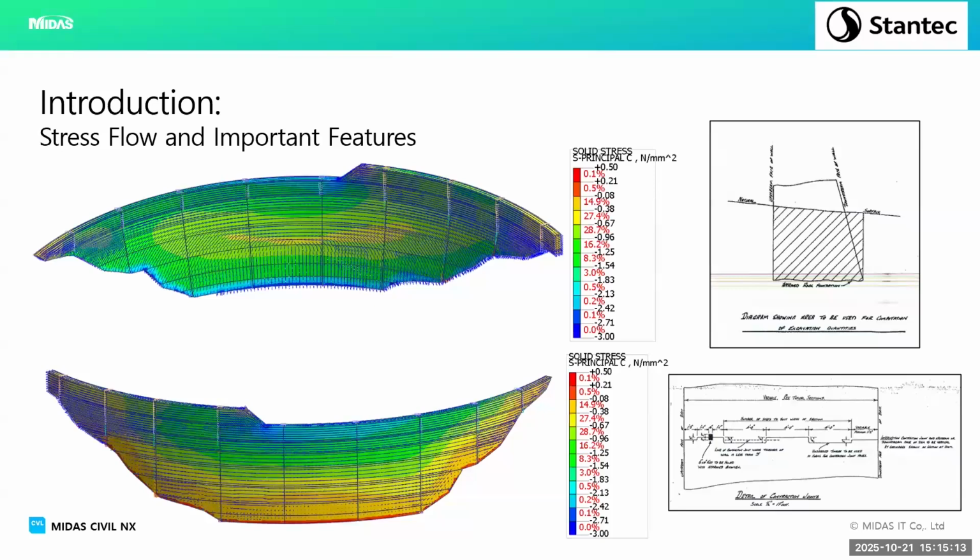And automatically that tells me, when I look further, that even if I get a vertical tension there, it's not necessarily the worst thing in the world because it's acting in hoop stress. So the only thing there that would really be significant is if there's a shear failure between those hoops. You don't get continuation of the arching. Then, I haven't put this in there, but the principal tension stresses on the upstream would be vertical. So just from looking at this, the model replicates what we could expect, and that's a positive outcome from the get-go. That's before we've gone any further.